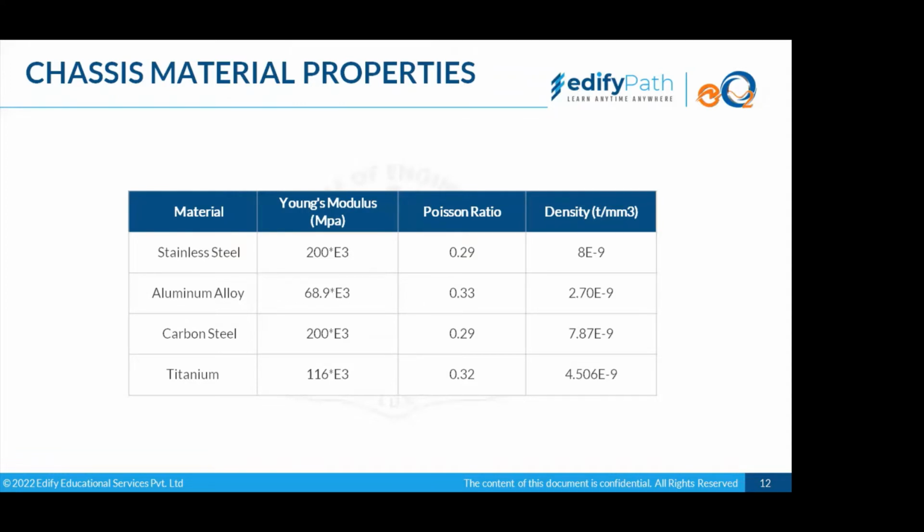So say there are longitudinal pulls in a bike also, when you are accelerating, some parts tend to be pushed or pulled. At that time we have to use a material whose Young's modulus is the highest, so that there is not much elongation happening.